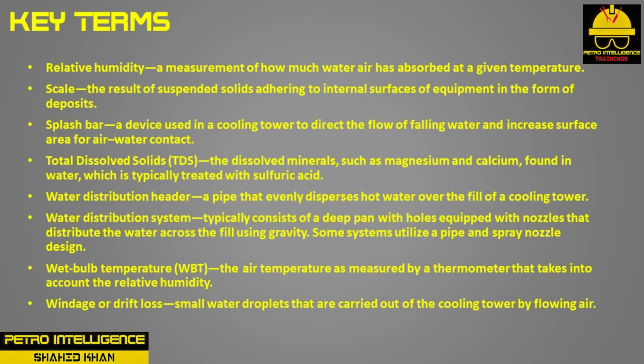Total dissolved solids, TDS, are the dissolved minerals, such as magnesium and calcium, found in water, which is typically treated with sulfuric acid. Water distribution header is a pipe that evenly disperses hot water over the fill of a cooling tower. Water distribution system is typically consisting of a deep pan with holes equipped with nozzles that distribute the water across the fill using gravity. Some systems utilize a pipe and spray nozzle design.